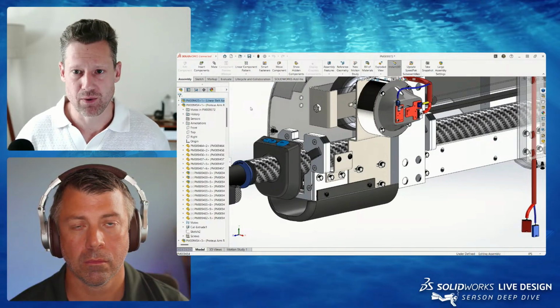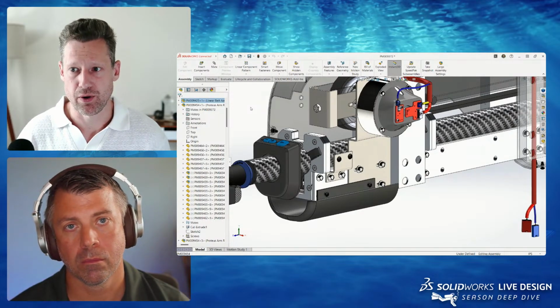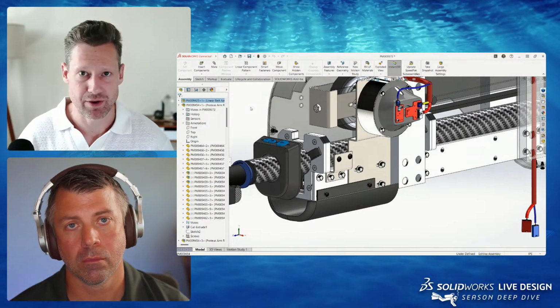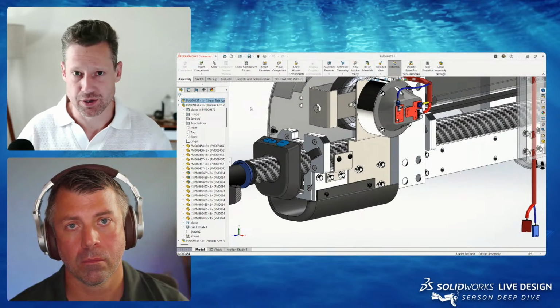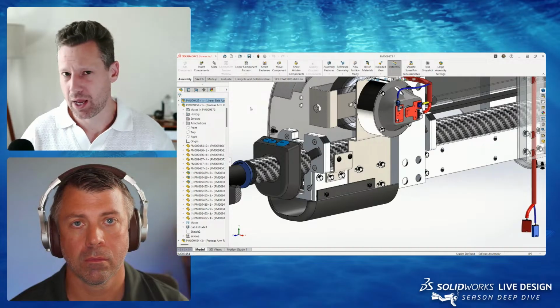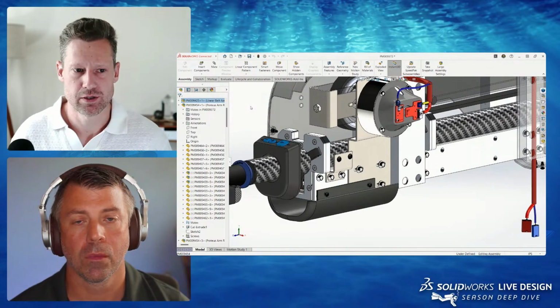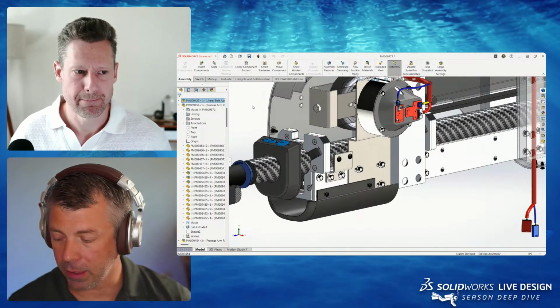So for computers like that, we may want to load it in large design review mode, which is very, very bare bones and really just loads, let's say, the graphic information. So it allows you to view, spin, rotate, zoom in, but you're not really able to edit anything until you actually resolve the components. So I hope that explains it. Yeah, that totally gets it.